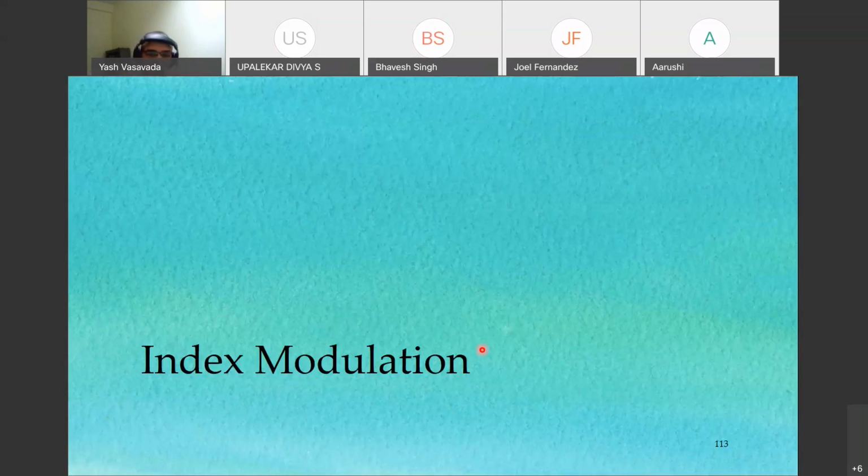Or actually the 8th antenna. All 0 is the first antenna, 0, 1, 1 is going to be the 8th antenna, and so on. So basically, I'm going to do exactly the same thing that I would have done in 16-QAM form. But in 16-QAM form, using these 4 bits, I was selecting one of the 16 symbols.